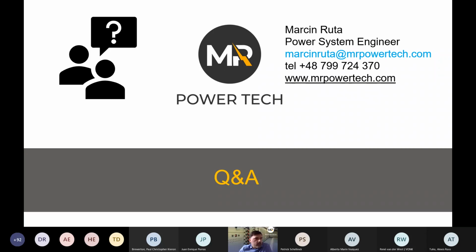For BESS, what type of arc flash study is required on the safety level? BESS is a battery energy storage system. On BESS, you have the AC side, which will be IEEE 1584, and of course it depends on the voltage level. Up to 15 kV, it will be IEEE 1584. On BESS you also have a DC side, which means you have to follow a DC arc flash study. It's up to you what you choose, because there is no written guide, but I recommend the Stokes and Oppenlander or Ammerman method to be used as a DC arc flash study. And if you use ETAP or SKM, you will have it included.